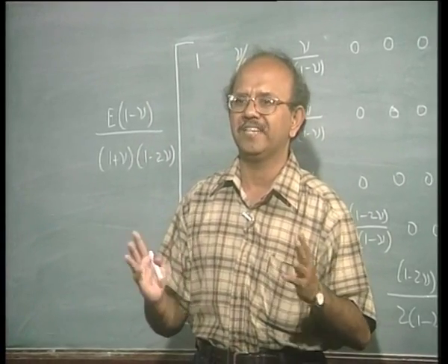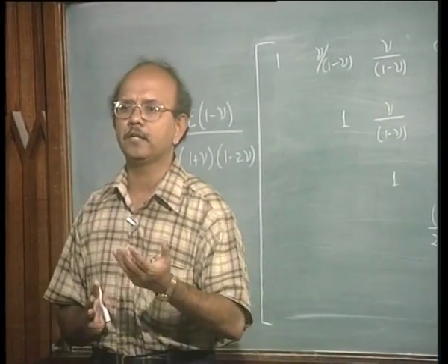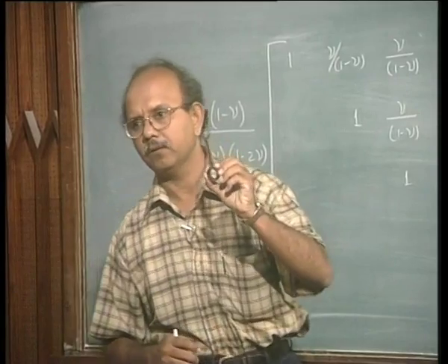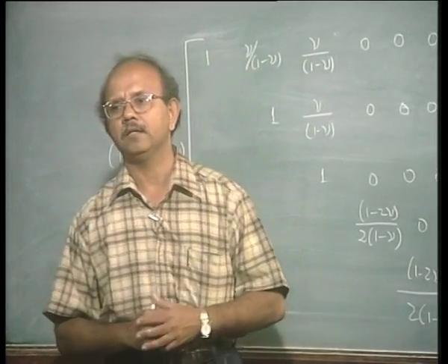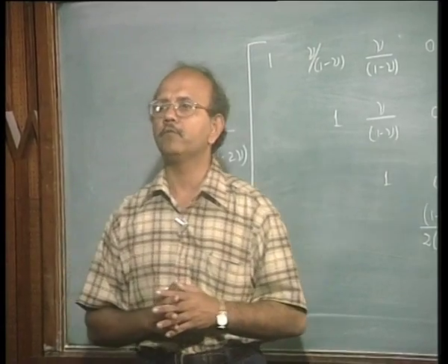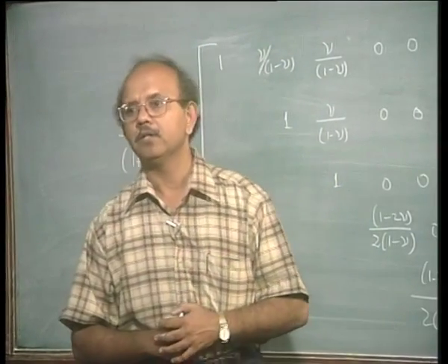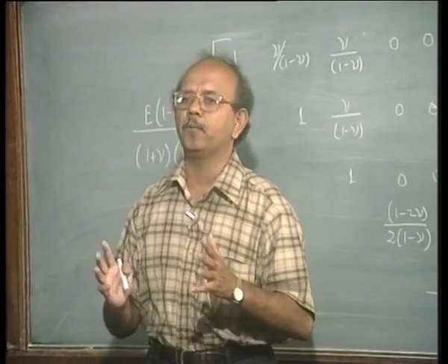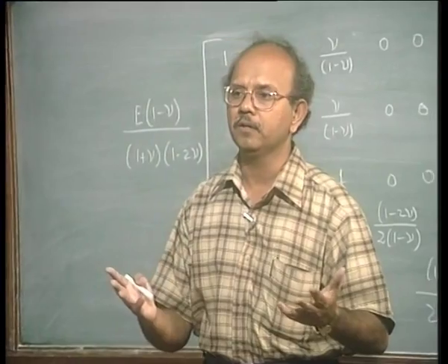behavior which I would call a 3-dimensional behavior, for which I had put down a 3D element. For example, we saw that for a connecting rod, this kind of connecting rod, we have to use a 3D element. And then we looked at certain other examples. For example, we looked at the LP rotor, and said that in order to study the LP rotor, we have to put down what is called an axisymmetric element. Now we also saw a gear, and we said that for the gear, depending upon its thickness, we can put either a plane stress or plane strain or maybe 3D and so on.